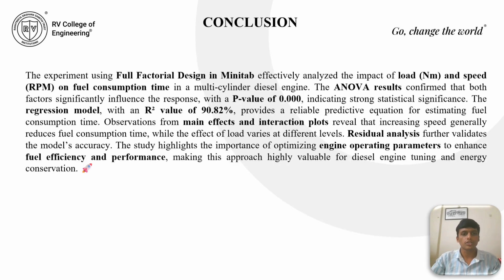And finally, the conclusion. Through this experiential learning experiment on a multi-cylinder diesel engine, we systematically analyzed the influence of load and speed on time using statistical tools. The Pareto chart helped us identify the most significant factor, while the main effects plot showed clear trends in how load and speed individually affect time. The interaction plot revealed the dependencies between these factors. And the residual plots validated our model's reliability, confirming normality, randomness, and absence of autocorrelation in error.